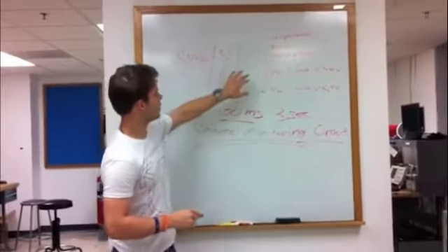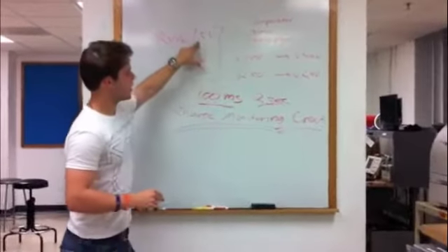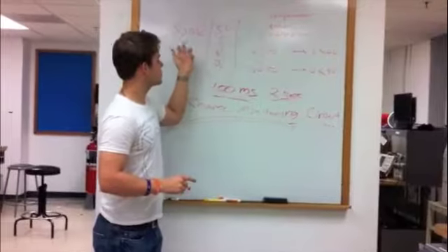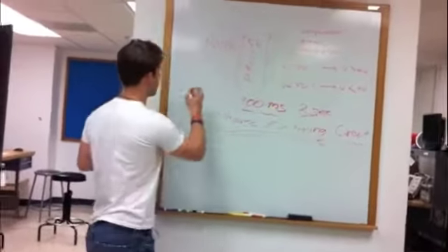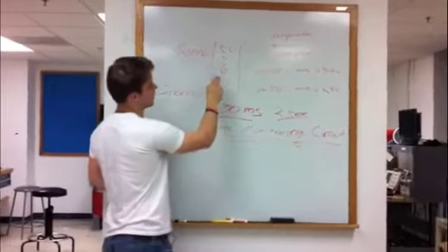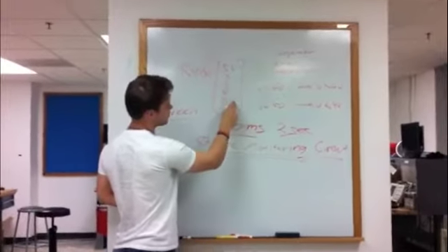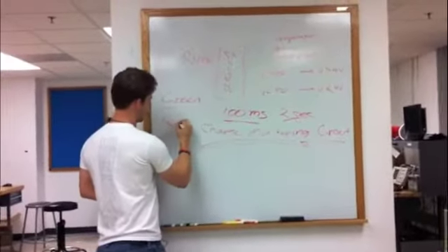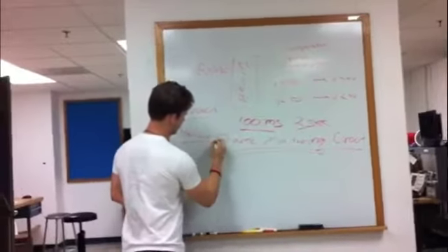And so, for the entire time that the capacitor is between 5 and 4 volts, the green LED will be on. And then, when the capacitor is between 4 and 3 volts, then the yellow LED will be on. This green LED and this yellow LED down here are the way that we can tell if the capacitor is above 50% or below 50%.